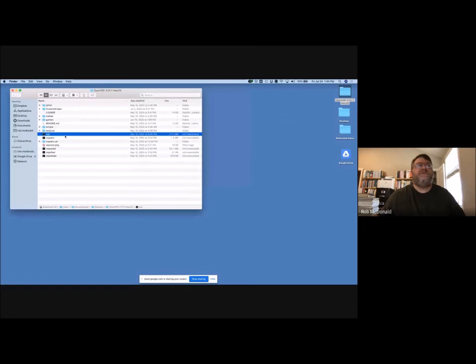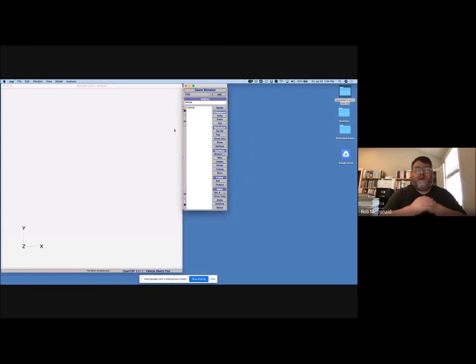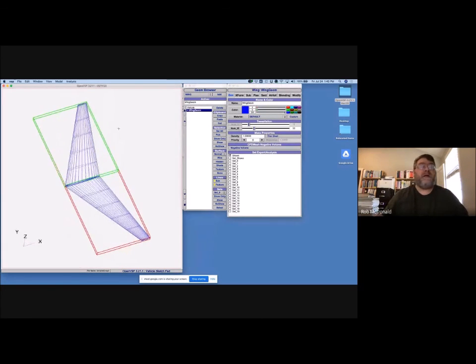So when you go to design a wing, you'd like to minimize drag. You obviously have to be trimmed, and you need a certain static margin when you're doing a flying wing. So you need it to be stable. And as much as aerospace engineers spend time talking about airfoils and fretting over airfoils, they're in certain ways not nearly as important as you might think. They can drive things, but a lot of an aircraft's, a wing's performance is really fundamentally driven by the plan form and the shape of the wing.